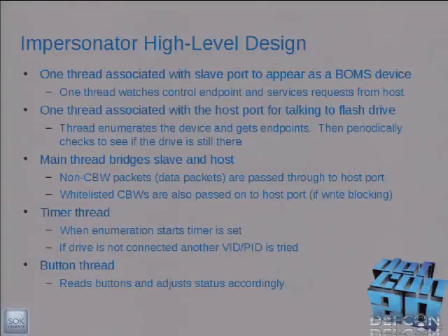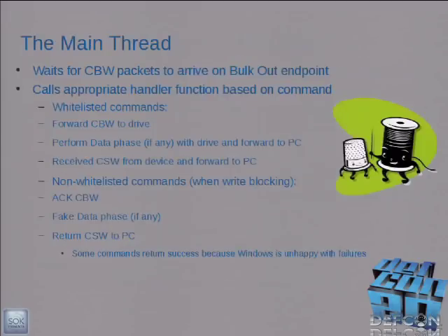In automatic mode, whenever the PC asks for a device descriptor, it says, someone's trying to talk to me, and it starts a timer. If they stop talking after a second and don't ask for additional descriptors, it says, someone's blocking me, I'll go to the next one. And that's how that works. There's also a thread for reading the buttons that come in.